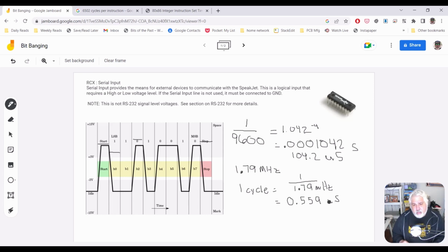However, you will have an advantage, because if you're using those kinds of processors to implement bit banging, you probably will already have very accurate delay timers at the microsecond level. So you won't have to do what I have to do on the 6502. You'll just call the delay function after you understand what your main code is running at. You'll call a delay for maybe 104 microseconds, let's say, if you're going 9600 baud, or maybe a little bit less than that because the instructions above it took some time. So you can tweak this delay number so that you can get the proper speed. And that's part of your testing scenario anyway. So knowing how I'm doing this with the Atari 800XL, let's take a look at an example of this working, and then we'll take a look at the 6502 assembly language.